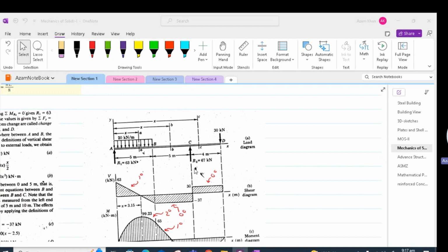When we say to define the whole beam, we mean to get the shear force and bending moment equations for the beam. The first x coordinate will capture the region AB where the UDL is continuous. After point B, the UDL becomes discontinuous. That is why region BC requires another x. Region CD has concentrated load effects at the boundaries. Hence, it would require another x.